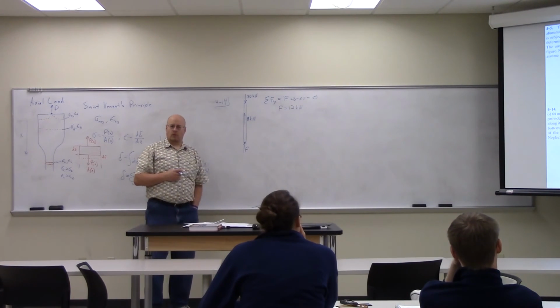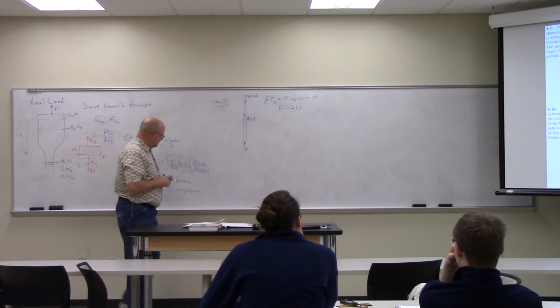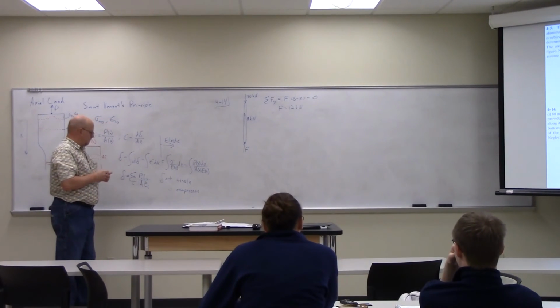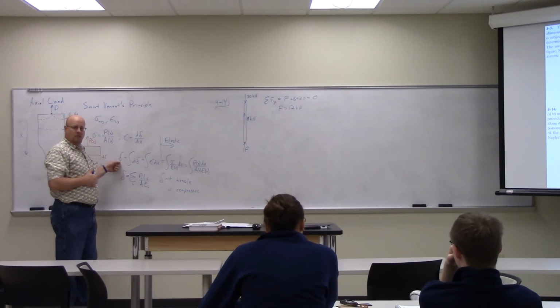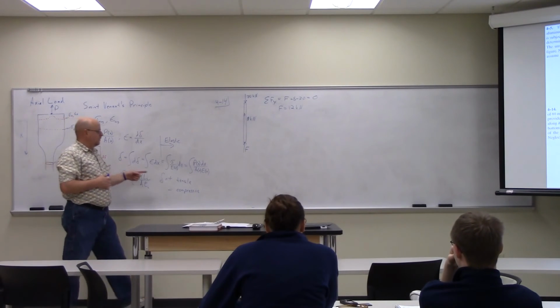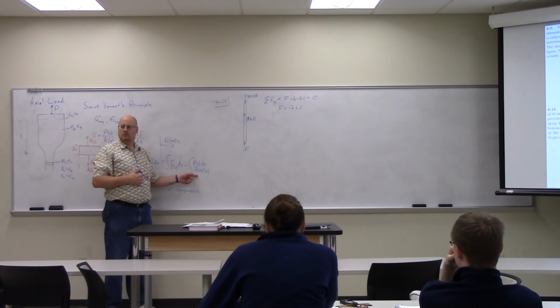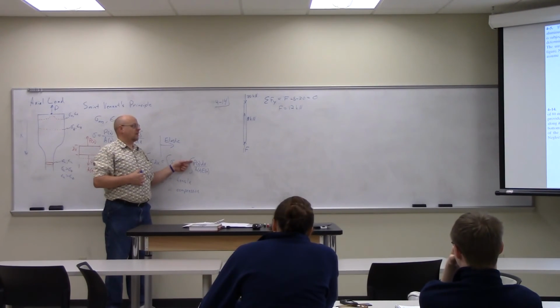So now we're going to find the displacement. Come back over here. Does the area change? Does E change? Does P change? Well, yes, it does actually. It changes when you hit the 8 kilonewtons, and it changes again when you get all the way to the bottom.